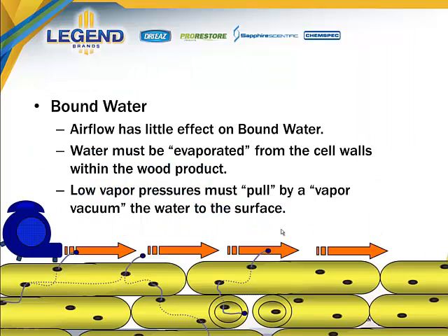To jump over this for now, however, air movement does still have a role in this process, but its role is dramatically diminished. It's still important, and we still can evaluate whether or not we have enough air movement in place using the same type of measurement. Simply take a thermal hygrometer and place that hygrometer along the surface of a building material that we are targeting, that we're drying, and verify that the humidity at that surface is the same as the humidity in the balance of the room. What you'll notice when you take this measurement is that you can significantly reduce the amount of air movement that you're using and still achieve that same humidity at both surface and the air above the surface. It does not take as much flow.